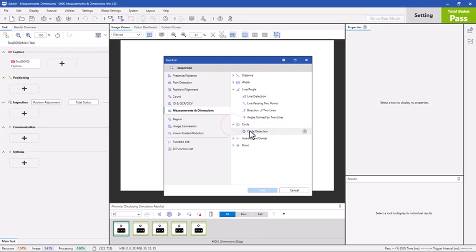Under the circle section, you can detect circles. So based on edge points, you can calculate the circle radius and position. You can do intersection points, where a line and vertical line intersect, where two lines intersect, the center of a quadrangle, or the midpoint between 2 points. And you can also detect points. So points can be detected with patterns: the pattern positions, edge positions, min and max position of an edge using the profile position tool, blob or grayscale blob. So you can detect points.